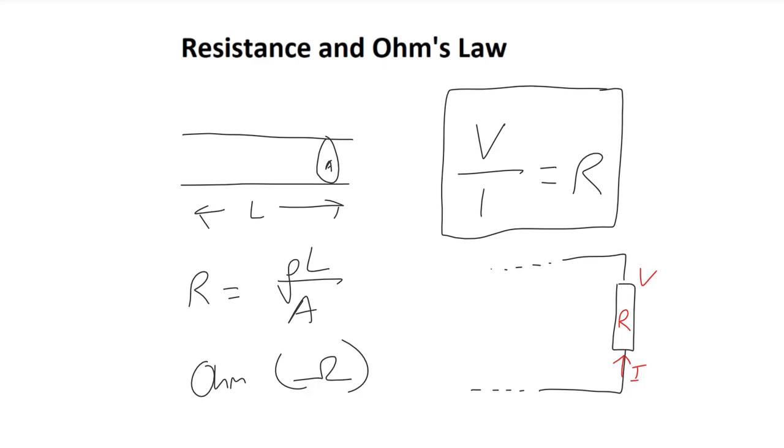The wires themselves, although very good conductors, also have an associated resistance with them. That resistance is very small, but it still exists. Even the battery itself will have an internal resistance associated with it. Because of this, the actual voltage supplied to a circuit is less than the voltage of the battery. In other words, the voltage supplied is equal to the EMF of the battery minus the voltage associated with the internal resistance of that component. This will be quantified better in a question at the end of this video.